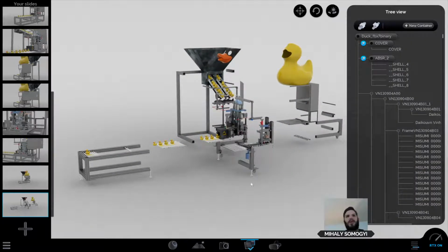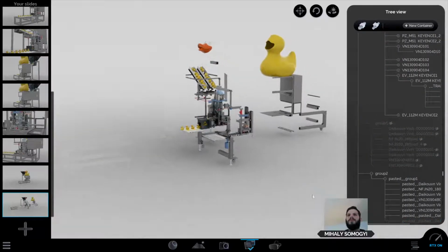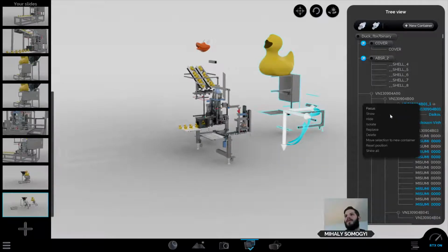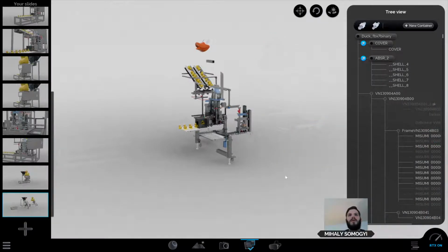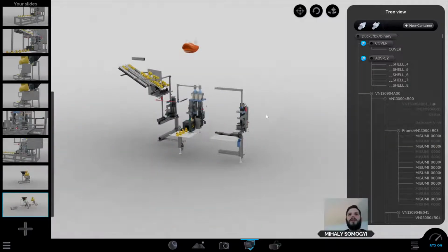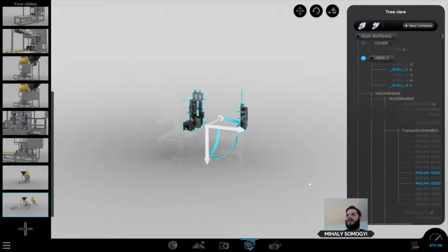And why not go a bit crazier with it and hide some more components. Basically, what I would like to highlight is only these central components. So what I'm going to do is use the rectangular to select them, then right click on a selected item and click isolate.